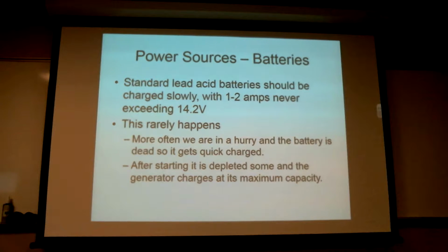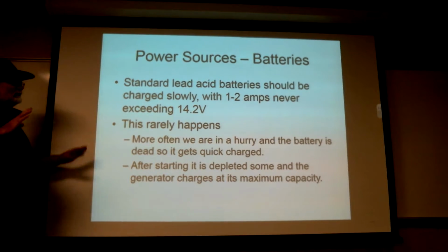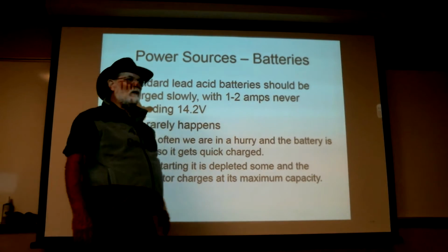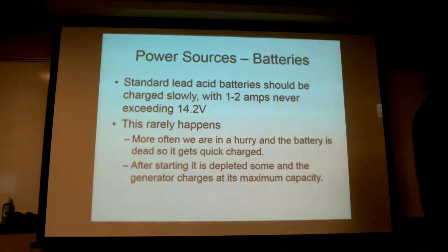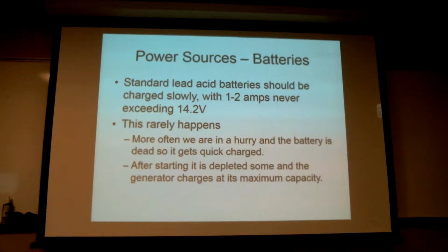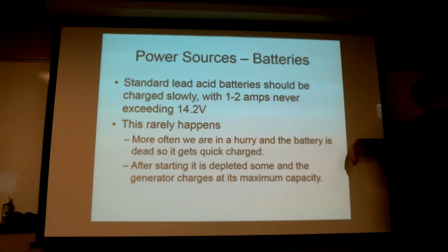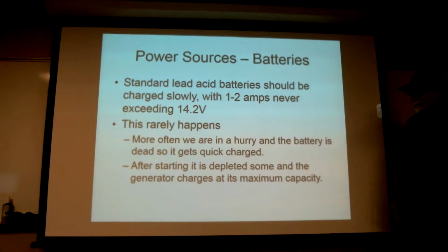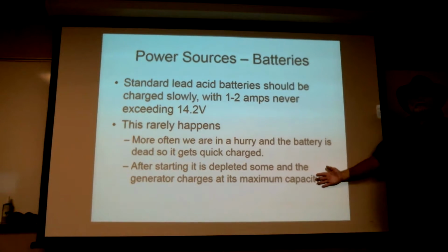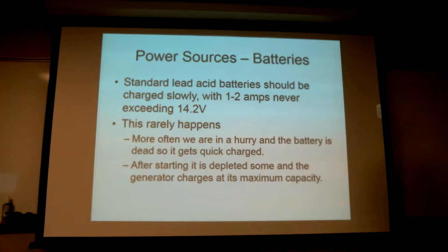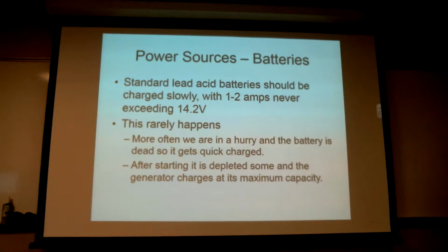So, as an almost universal rule, I say standard lead acid batteries. The truth is, all batteries should be charged at a pretty low rate if we want to increase their lifespan. The other thing, we talked a little bit about, we get in a hurry, slam it with some juice, start things up, and away we go. But the truth is, every time you go to start your engine, I've just discharged the battery some.